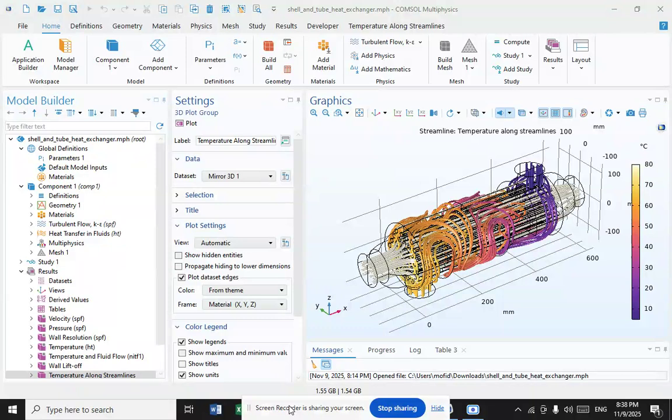There are many types of permanently bonded plate heat exchangers, such as dip brazed, vacuum brazed, and welded plate varieties, and they are often specified for closed loop applications such as refrigeration.